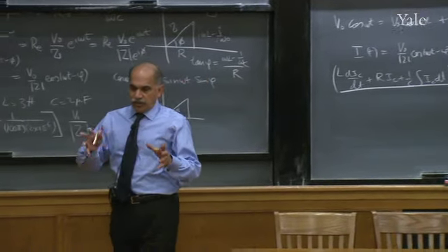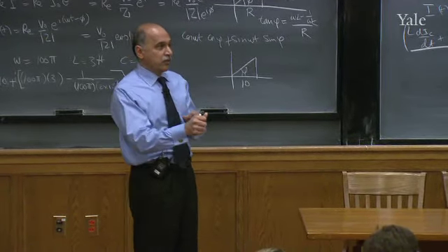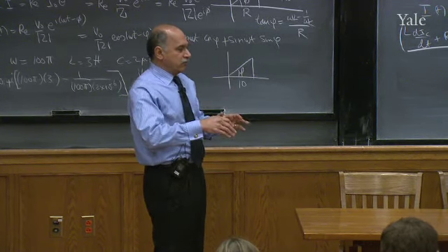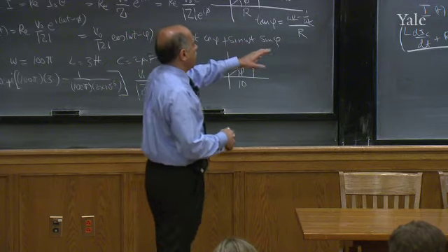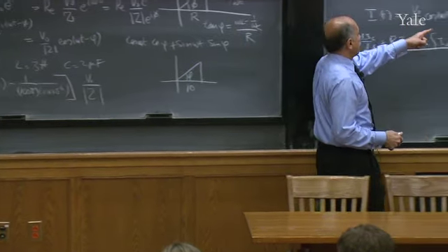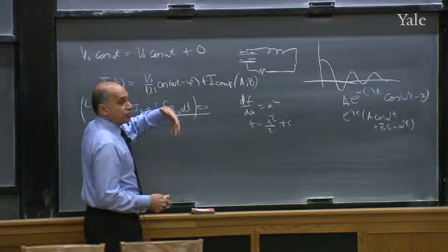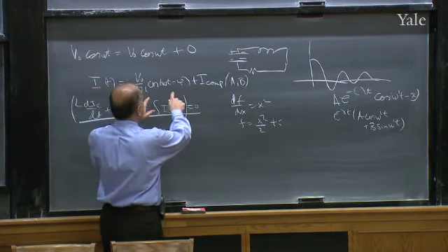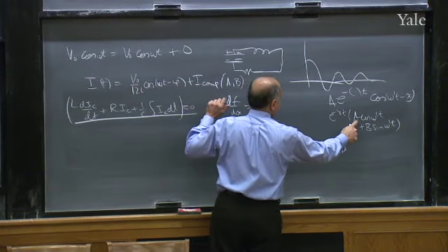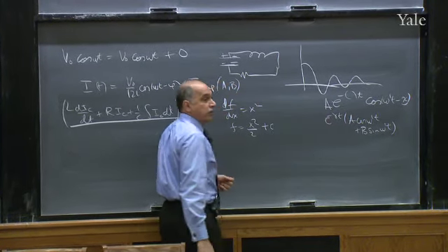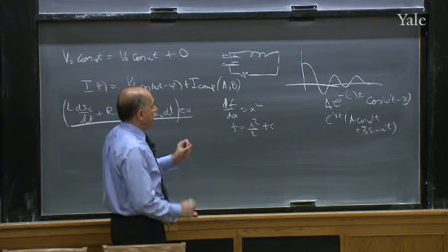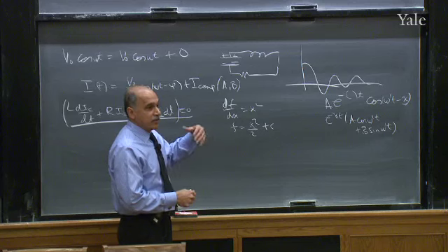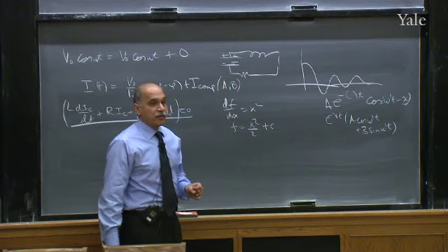In other words, if you took the LCR circuit and took a generator and you hooked it up, from the instant you hooked it up, it won't immediately assume this form that I have here. Because, for example, at t equal to 0, maybe the current is 0 in the real problem. This current doesn't vanish. But you should add to this function, choosing a and b so that the current vanishes at t equal to 0. You can fit the actual experiment to the solution by choosing a and b to match the initial current and, say, the initial charge on the capacitor.